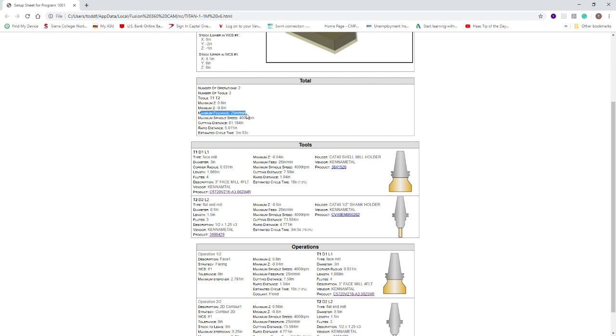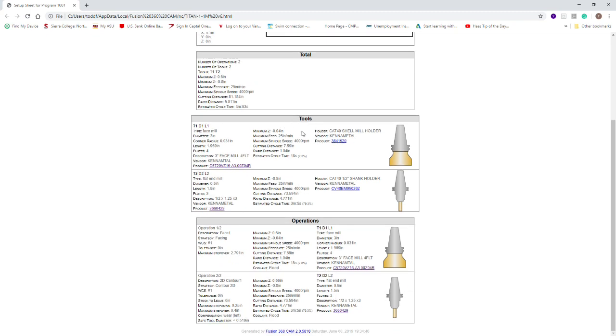We're also going to be looking at your maximum feed rate and your RPMs to make sure they're in line with our standards for the lab for safety. It's a good way to self-screen too if you made a mistake. If you accidentally punched in 250 here, it'll show up there. Okay. Then you have a tool list, which is a list of every tool you're using. Then there's a list of operations that those tools do with their own minimum, maximum, and RPM rates.